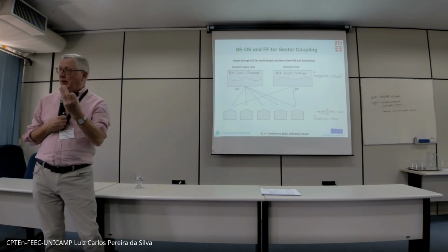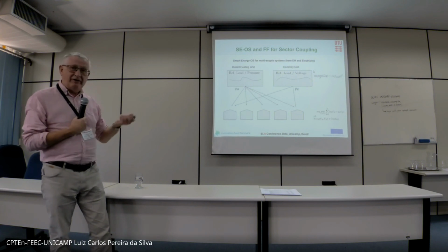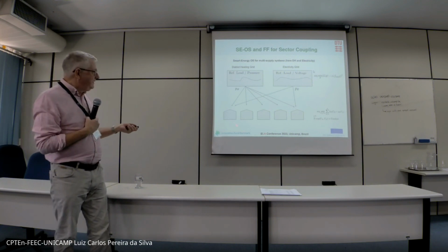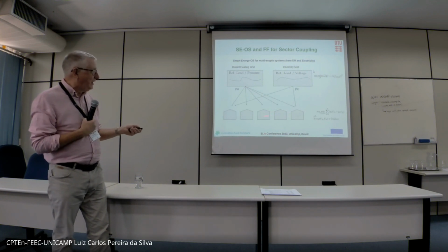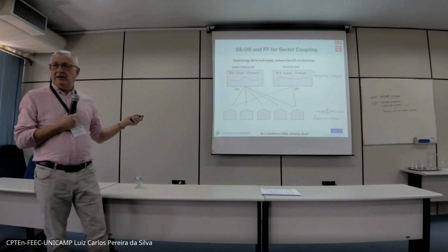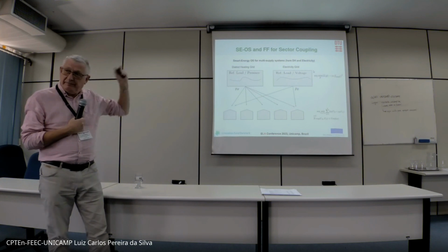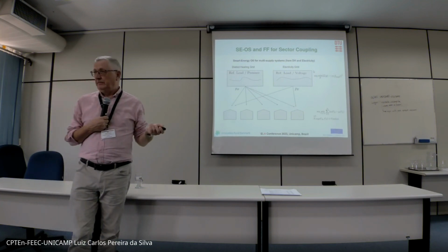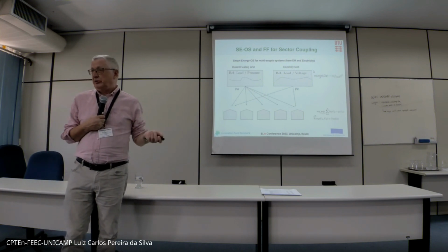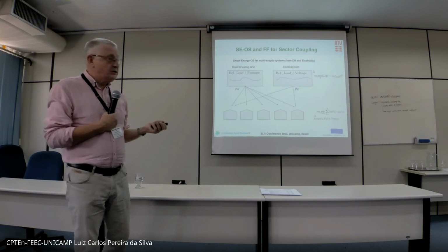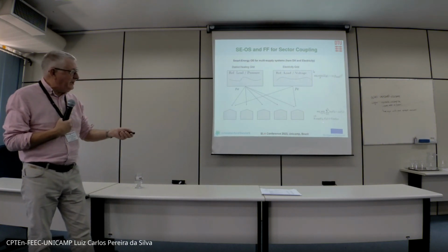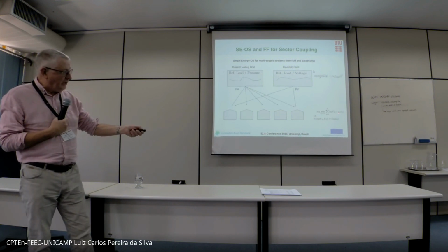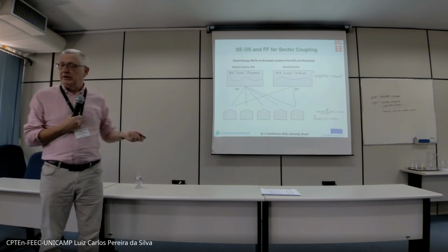Another thing is we need to do sector coupling, as I said initially. In Denmark, we have a lot of district heating. I think 60-70% of the houses are heated by district heating, correct me if I'm wrong. And this is just an example where we have 5 houses all having district heating, where we might do peak shaving, like I did for the electricity case before, and we control the pressure difference, like I also showed before. And then 2 of these houses have also installed a heat pump, because we would like to reduce the number of times the wind turbines are stopped. So the hierarchy of controllers can easily be extended to this setting with sector coupling. It's a trivial thing to add another energy supplier, so we can automatically switch between district heating and electricity.